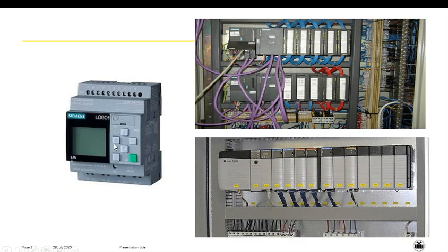So this is one type of PLC of the Siemens company. These are inputs, these are outputs, and this is your CPU, and the power supply is there. This is a fixed kind of PLC whose inputs and outputs you cannot extend. If we can extend the IOs of a PLC, then that PLC is called a modular PLC. There is a separate CPU and separate racks in which you can mount the digital input, digital output, analog input and analog outputs.